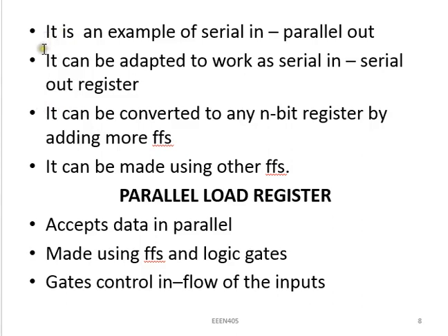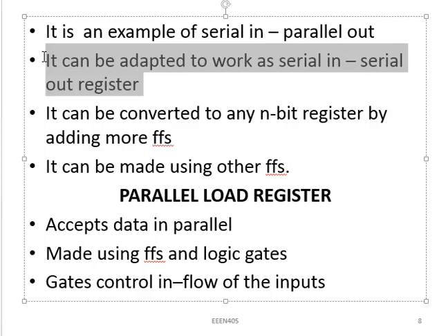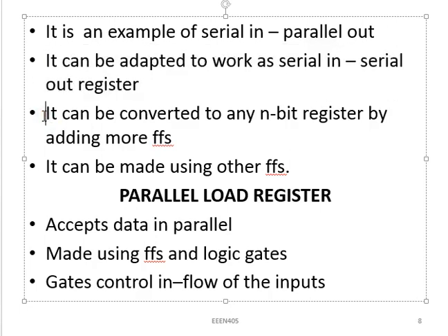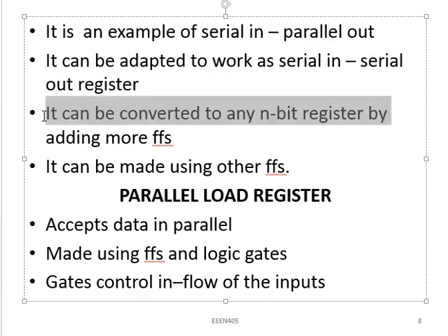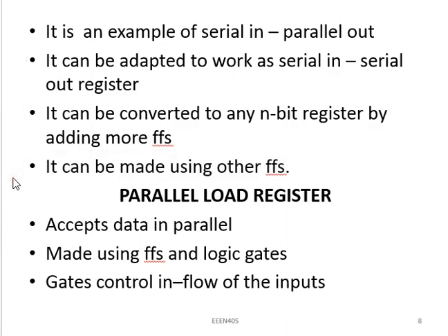So as I have said, it can be converted to work in serial in and serial out, as I have just illustrated. And of course here we illustrated only a 4-bit serial load register, but we can convert it to any number of bits, n bits, if we increase the number of flip-flops we use there. And of course here we have seen how this serial load register is designed using the flip-flops, but at the same time you can use other flip-flops to design it, but it will be a bit more complex than this, because their next state equations are quite different from that of